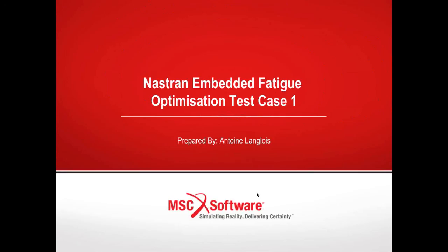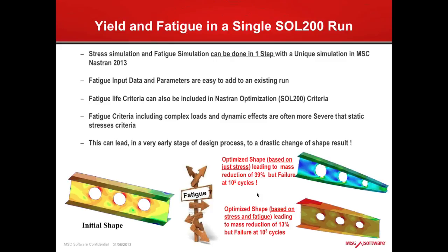I have a couple of very short examples on optimization, and I'm going to show these to bring out 2 different ways of considering the use of optimization in fatigue. The first is a very interesting concept: generally in fatigue analysis, we normally only check for fatigue as a parameter rather late on in most design processes. So we typically design for other things, and then right at the end we check to see whether fatigue is okay. What that means here is we start off with a beam as shown on the left-hand side of this slide, and we proceed with our design, and we only use stress as the controlling parameter.